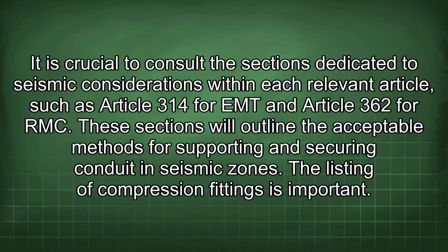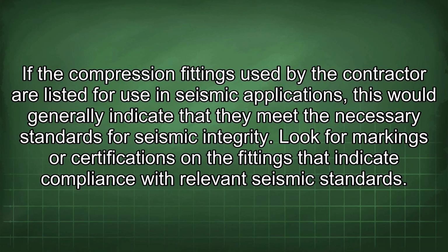The listing of compression fittings is important. If the compression fittings used by the contractor are listed for use in seismic applications, this would generally indicate that they meet the necessary standards for seismic integrity. Look for markings or certifications on the fittings that indicate compliance with relevant seismic standards.